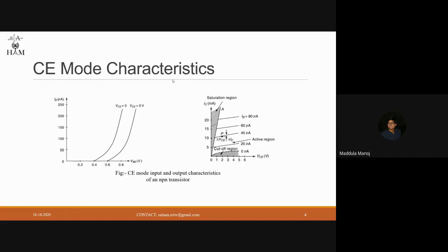So there are three modes of operation for a BJT transistor. When input less than threshold is applied, then the transistor is off, and that is called cutoff. And when an adequate amount of input is applied, a certain amount of current flows through the transistor and it operates in the linear region. But when you apply a high input voltage, the maximum amount of current that can flow through the transistor is limited by the electrons and the speed of electrons. So when that happens, the transistor actually saturates. So the maximum current is limited. So that's what saturation is.